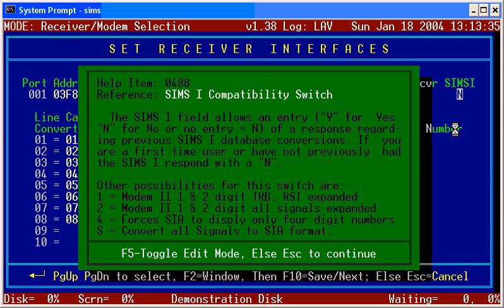This was done because, as we know, a lot of the Radionics panels sent in different trouble signals that were actually test signals or system reset signals, and if we want to be able to deal with these across the board, it's necessary we have total programmability regarding these troubles and restorals.